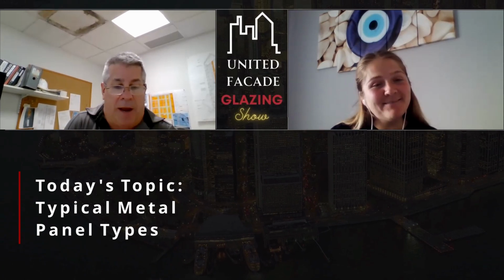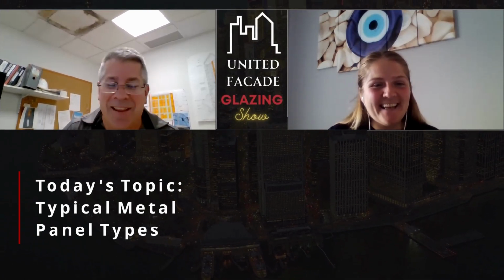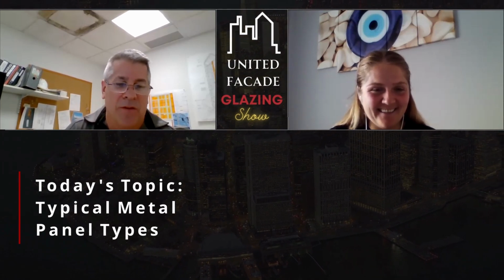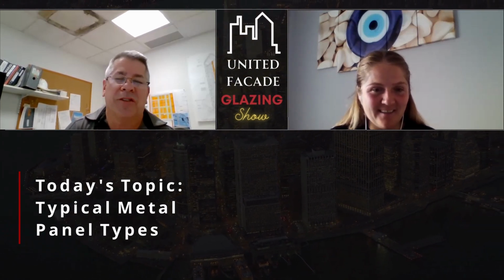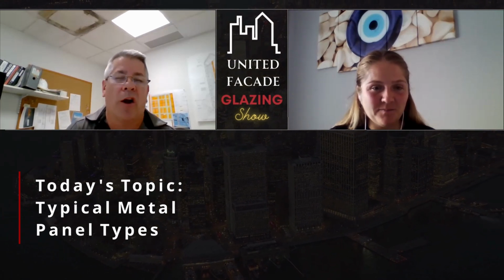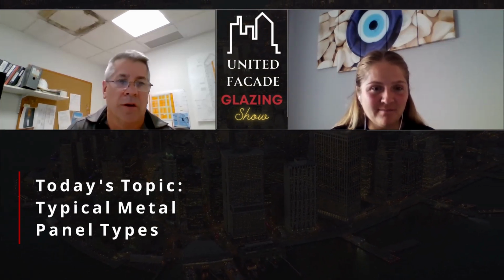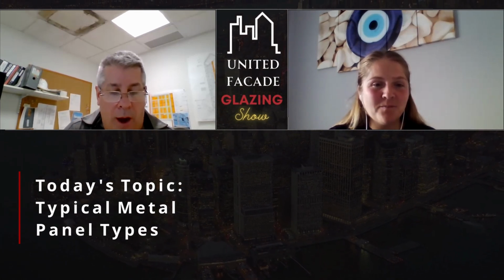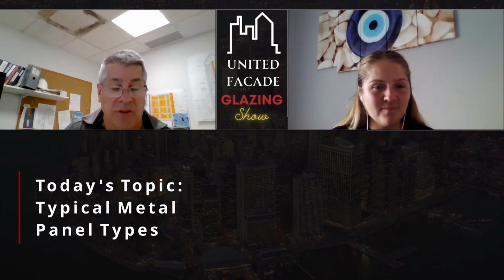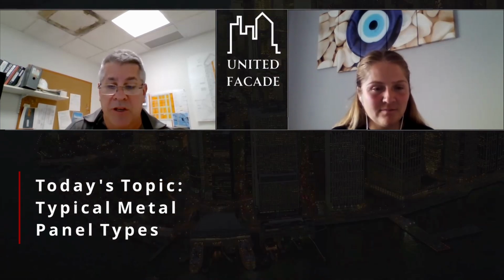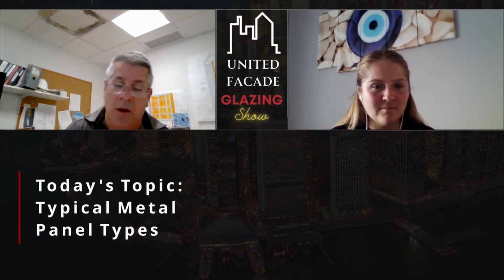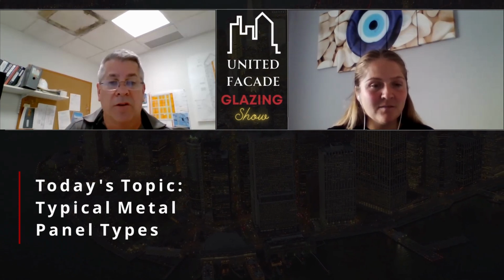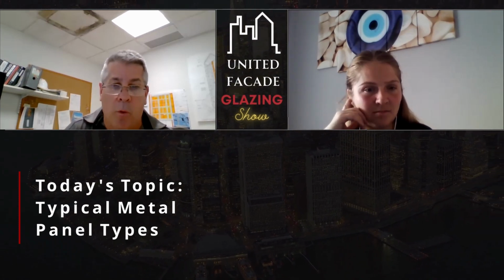Another type of panel, and again, you'll see those. So many buildings have these. This could be around the window system. It could be on a sheer wall where you have no windows and just a panel wall going up. And the other positive on these ACM panels is that it's a very lightweight panel, because you have a very thin layer of aluminum skin on each side and a plastic core. It's very lightweight, so it's very easy to maneuver manpower-wise.